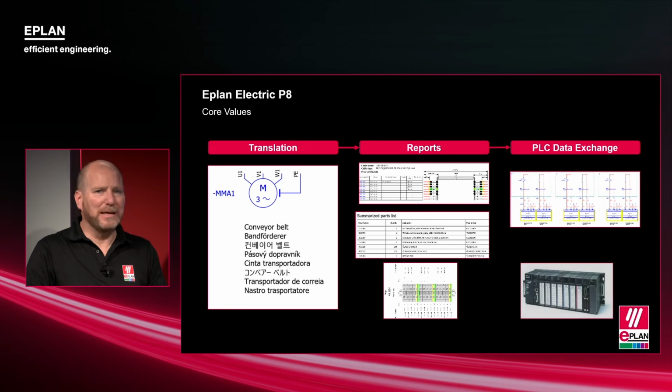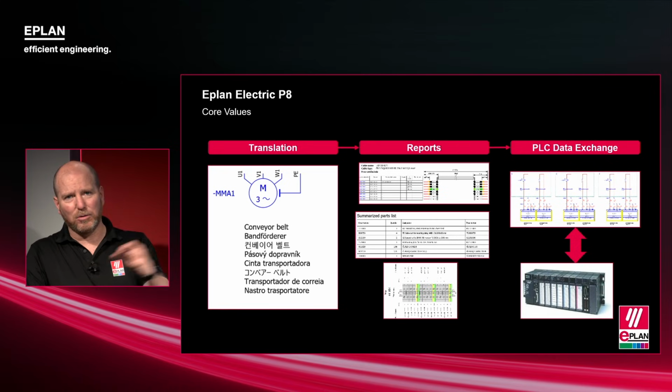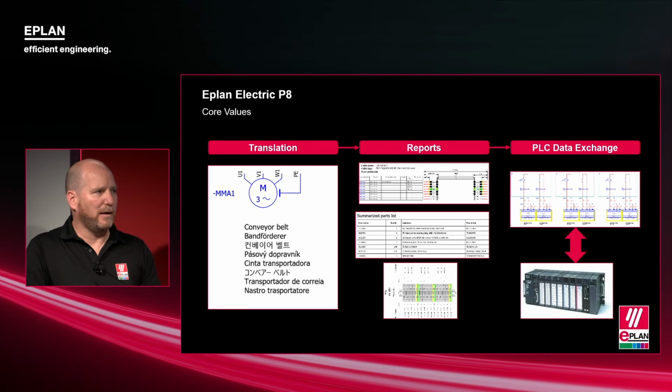And finally, PLC data exchange. In the schematics, you capture all of your I/O information, inputs, outputs, you capture your PLC systems, but now the programmers, they don't want to manually take it off, right? They want to be able to automatically take all the data you created in ePlan and then leverage that to start writing their code.